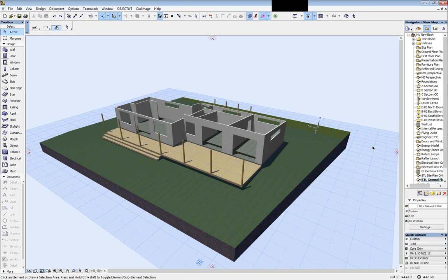The other one that's missing is the weatherboards, because their profile is about 35 millimeters and 0.3 will not print on the printer. And the other issue we experienced was cavities. So the cavity that we had between the weatherboard and the wall, or the roof covering on the roof, meant that the bit that even did try to print wouldn't stick because there was a void, so when it did finally print, it would fall off. So weatherboards too thin to print and the cavity creates some issues as well, so we've excluded those.